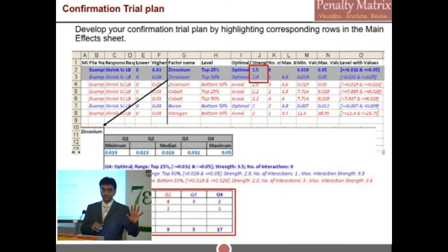At the moment, we got only one, but the study becomes challenging if you have conflicting responses. That is, one chemistry which minimizes shrinkage defect does so at the cost of tensile strength. So one which will optimize shrinkage will adversely influence tensile strength. And that's where you want to come up with a common ground. We'll see that in the second case study, because that thinking is also different from Six Sigma philosophy.